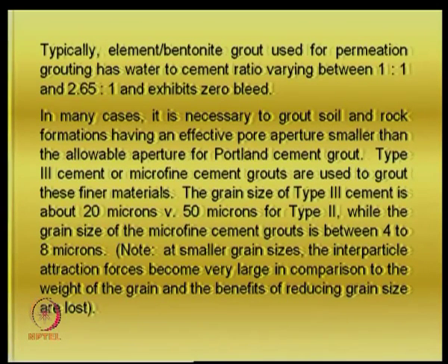So you have to try to balance the gravity and the interparticle forces. You must be able to balance so that the grout can go to the required destination. The force of weight is required to some extent, but if at the same time it just starts getting suspended in the form of a few particles in the grout, then the purpose is not served. There should be a balance of the forces of gravity and interparticle forces, and that is how the grout is chosen.